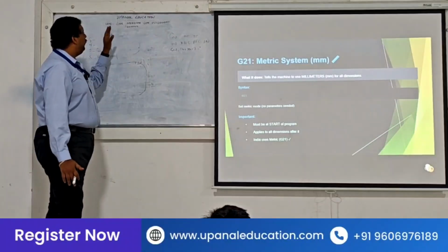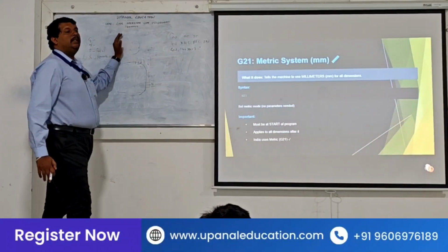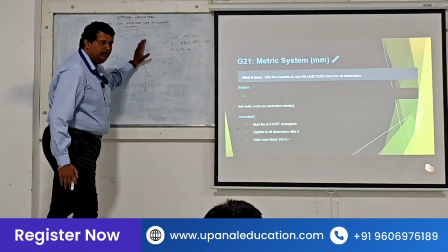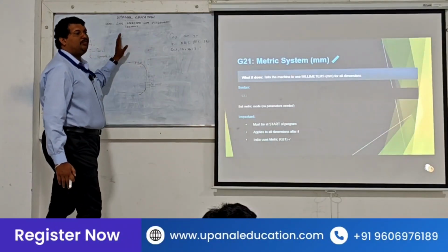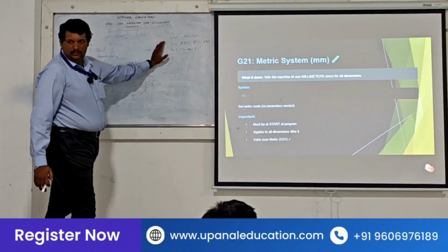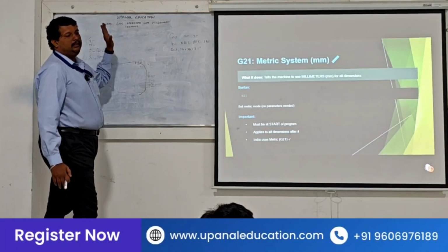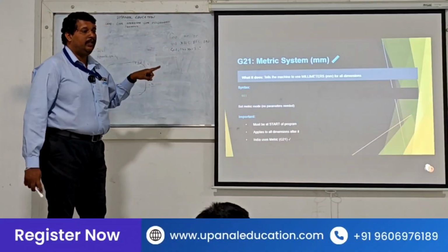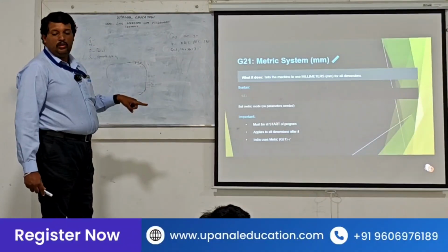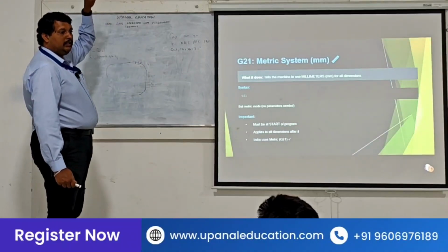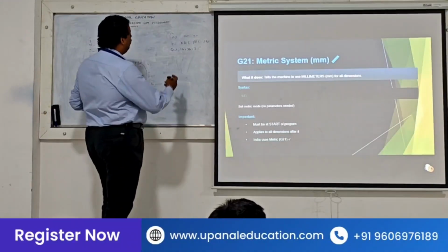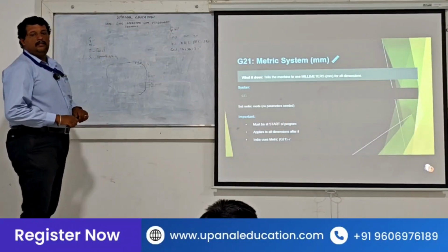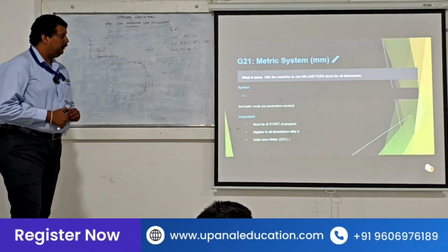If I give you 100, you have to move only 100 mm. If I give you the value of 50, you have to move only 50 mm. You should not go 50 centimeters, or 50 inches or anything. So we will have only mm and inches. And where should this come? It should come at the starting. So G21 is the metric system, mm.